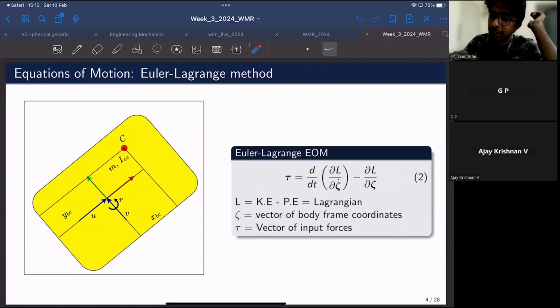If the entire rigid body is living on the datum itself, you can fix the datum to be the zero point, and you can consider the potential energy of that point to be zero. So for this case of mobile robots, you can consider the potential energy to be zero. But that cannot be generalized for systems that live out of plane, that have spatial coordinates.